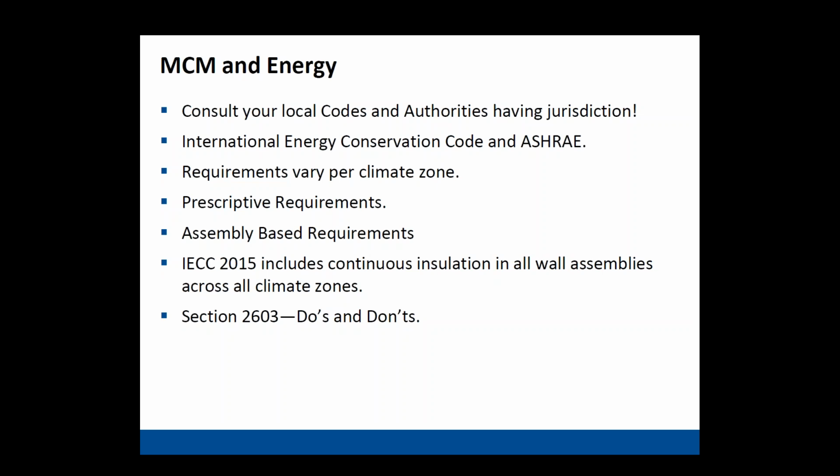If a project is NFPA 285, it has to be NFPA 285 compliant. If it's over polyiso, it has to go to a fire retardant core because there is no testing with a polyethylene core in a 285 situation. So that's the most commonly misspecified item that we are seeing of late. And if you're not working with the top shelf fabricators, if you will, they will miss that every single time.